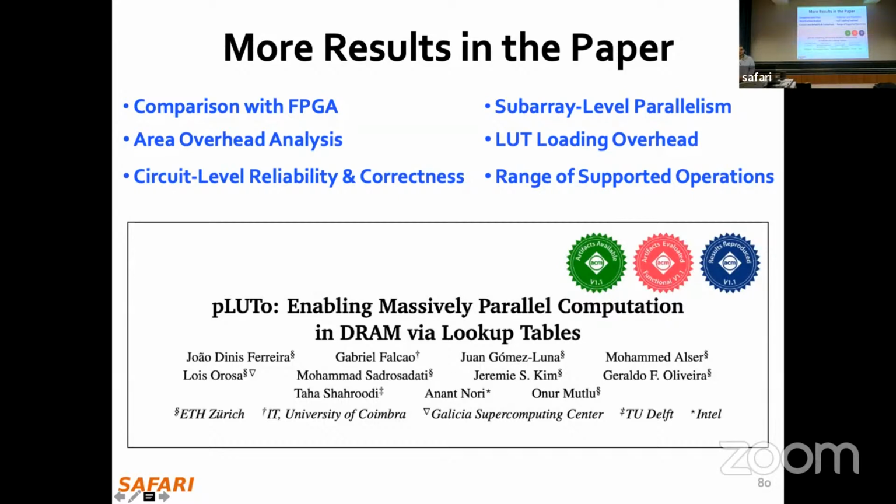There is actually a paper that does exactly that. It implements a 6-input lookup table, which is exactly what FPGAs do, using DRAM itself. The goal there is a bit different than pLUTo. pLUTo wants to extend the operations of processing-using-DRAM. Over there, the goal was to implement an FPGA architecture using DRAM cells. There is some intersection between those two for sure, but it's a bit different.